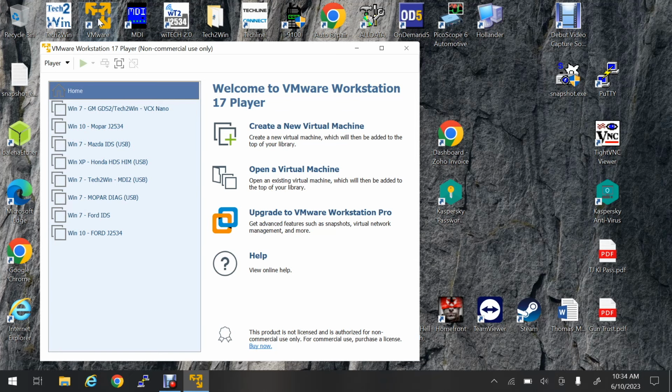So you can run into a situation now that you didn't used to run into. It used to be you could put your somewhat questionable copy of Techline and GDS on your desktop, and you could still program. You could still have those all on one machine. What they did on the new Techline Connect programming is it now checks the version of GDS and Techline, and it updates it every time. However, that kills your activation.